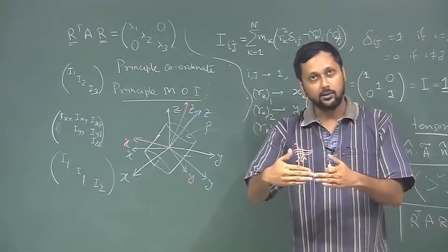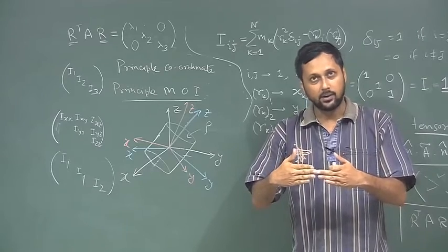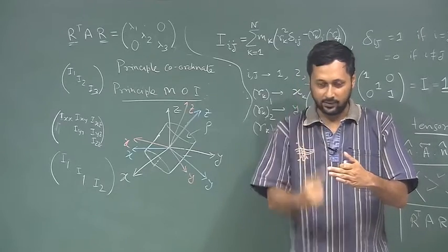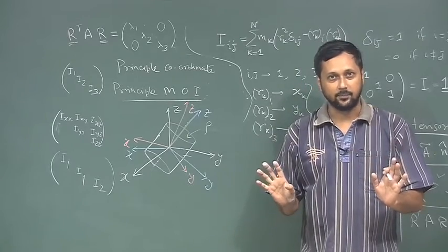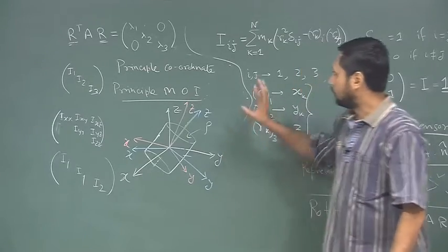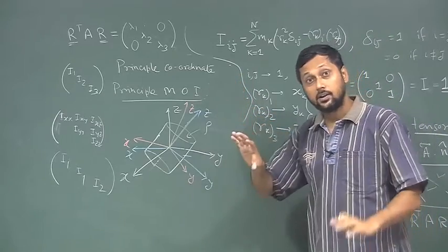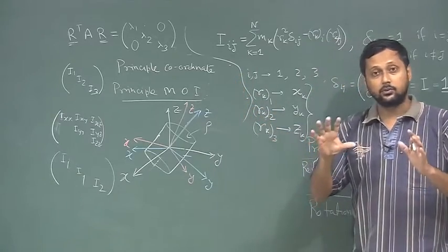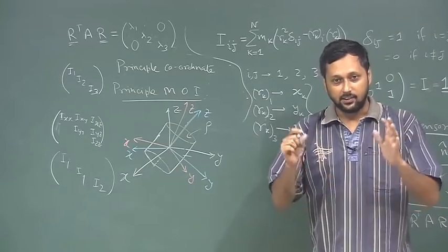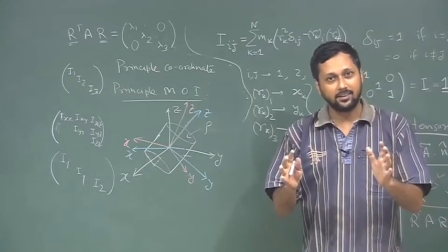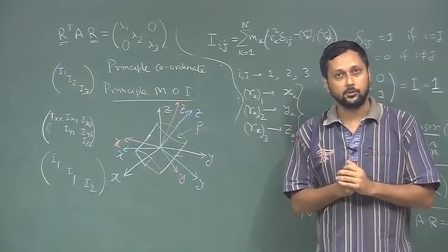Does not matter where I choose it, I just need two perpendicular axes, okay, and one z axis that runs along the bottle, that will be the symmetric axis. So, typically for moment of inertia, because it is a property which is strongly dependent on the mass distribution of the system, the geometrical symmetry axes are the principal moments of inertia axes.